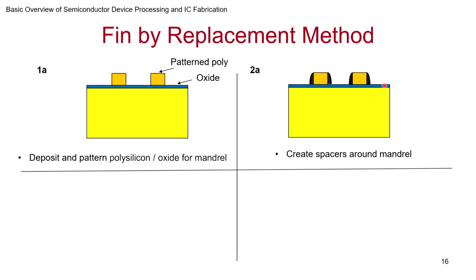You can see this is very similar to when you are sweeping, say, and there is a step. You'll find that dust will collect at the corners, right? It's very similar to that. So here the oxide or nitride has formed in these corners. So you deposited it on top and you etched it, as we saw earlier also. So then you get this spacer structure. Now these spacer structures, mind you, can be very narrow, much narrower than what you can achieve with lithography.